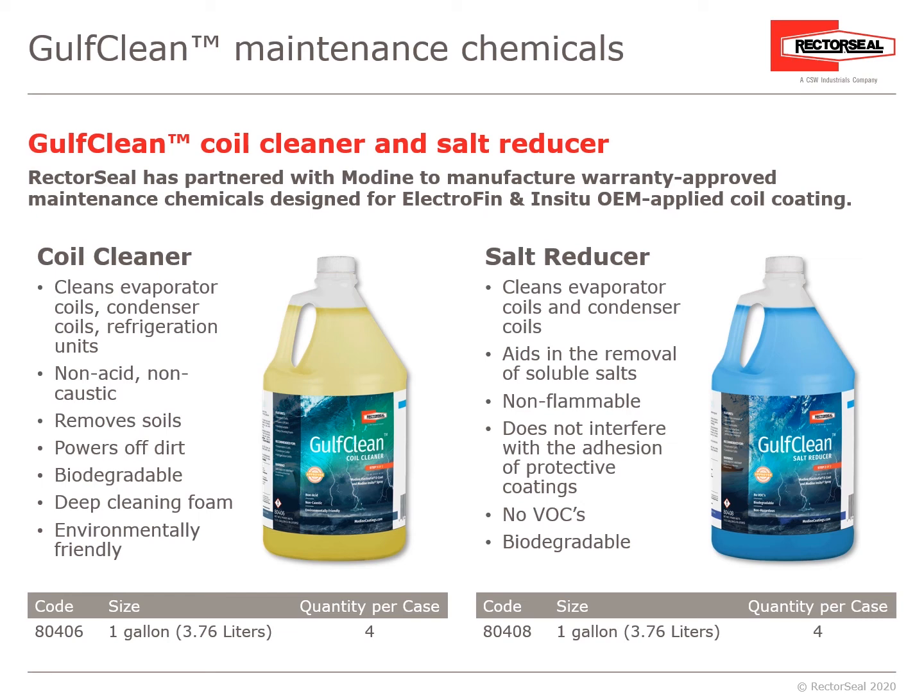Also with Gulf Clean is the salt reducer. It cleans the evaporator coils and condenser coils. It aids in the removal of soluble salts. It's non-flammable. It does not interfere with the adhesion of protective coatings, no VOCs, and it is biodegradable. Both of these products should be used every 6 months and again are the only Modine CIS coatings approved 2-step coil cleaner and salt reducer.